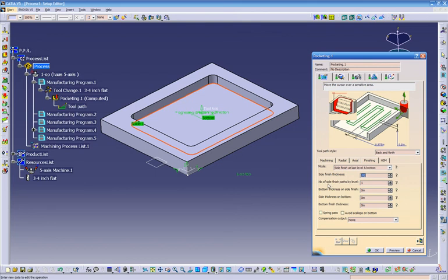Then it's going to ask us number of side finish passes by level. So it's going to ask us how many passes do we want. It says 1, bottom, thickness, and side finish pass. Side, thickness at bottom, everything is common sense. And then if you don't know what it does, you just click on the question mark. See bottom finish. Let's make this 20,000. So right now I just give it a finish on the bottom and a finish on the wall.